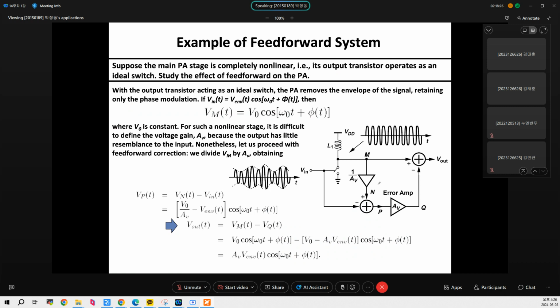As we observed, the switching mode power amplifier is completely nonlinear. Its output transistor operates as a switch. Since it's operating as a switch, the output must be fixed like this, with no AM amplitude information at all at the output. That's why we use switch mode power amplifiers only for PSK, MPSK. But we're going to learn polar modulation next